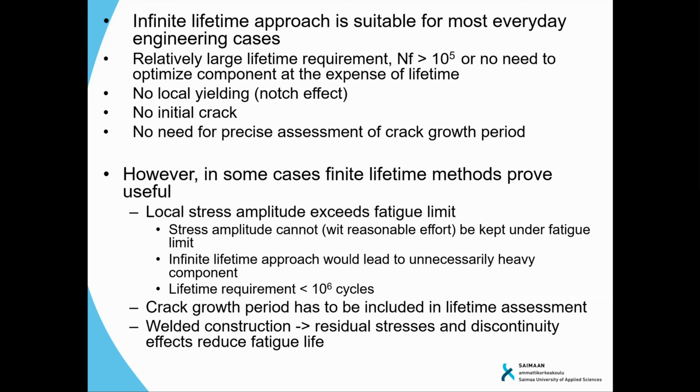So, as mentioned, this infinite lifetime approach is suitable for most cases in everyday engineering. It is good for relatively large lifetime requirements because we understand that if we calculate the component against infinite lifetime, the number of cycles from the application is usually quite high. It could be, for example, a rotating machine that is spinning at 1500 RPM, and therefore the number of cycles is really high.